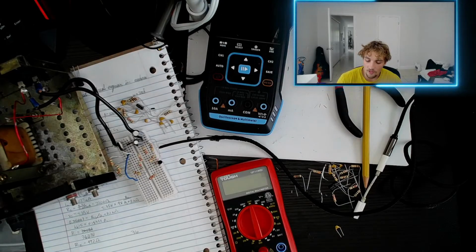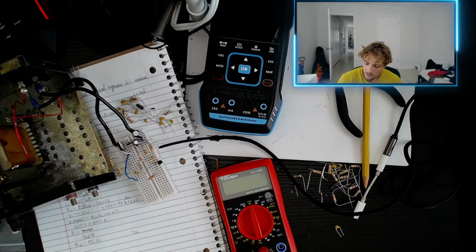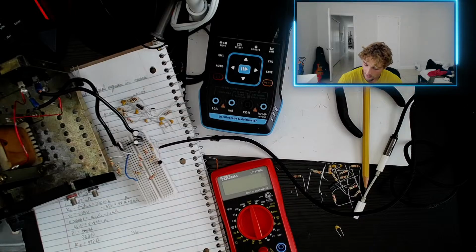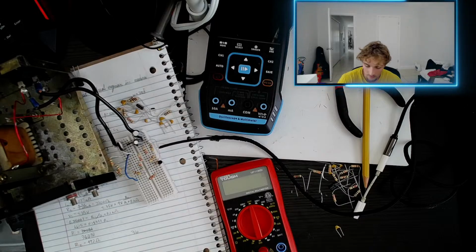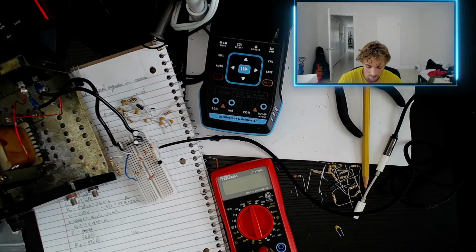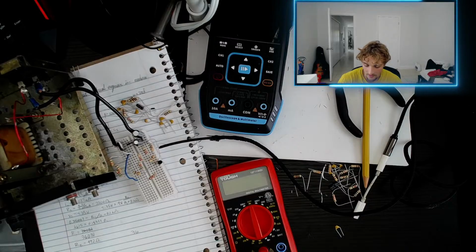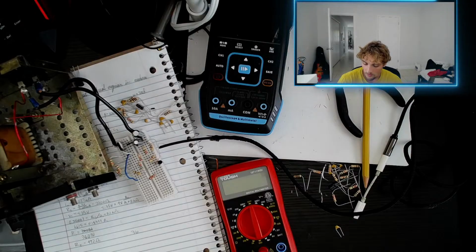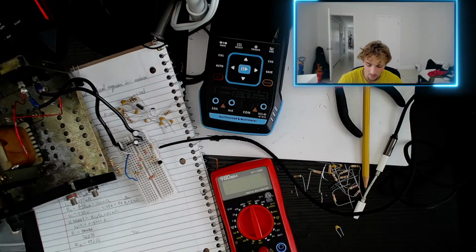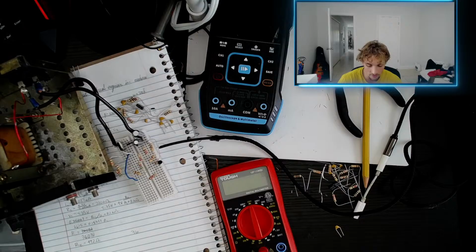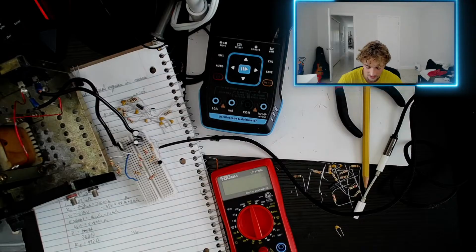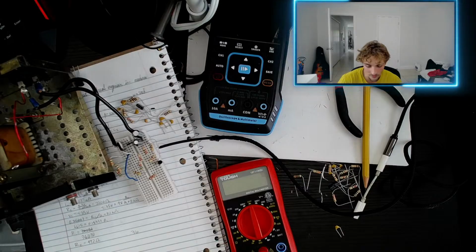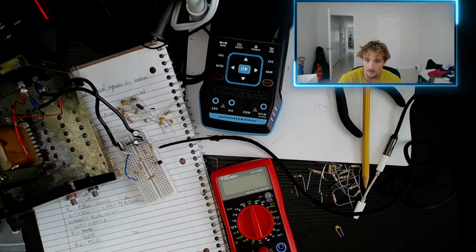Considering that we have 0.62 volts across our base to emitter junction of our transistor, we still might be in the operating or active region. So it's not very close to what I calculated. Now, why is that? I don't know, because as far as the research I've done, people don't really take into account any other portions of the network when calculating the resistance of the voltage divider for the base. So I'm not really sure why it's being so affected.